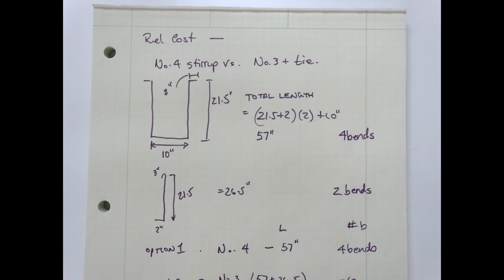So let's figure it out. There's another piece of information on this table. We only ever used 2 of them, right? We used the diameter in inches, do the bars fit? We used the area, how much load can they carry? This middle column is the weight of the bars in pounds per foot. So let's check it out.